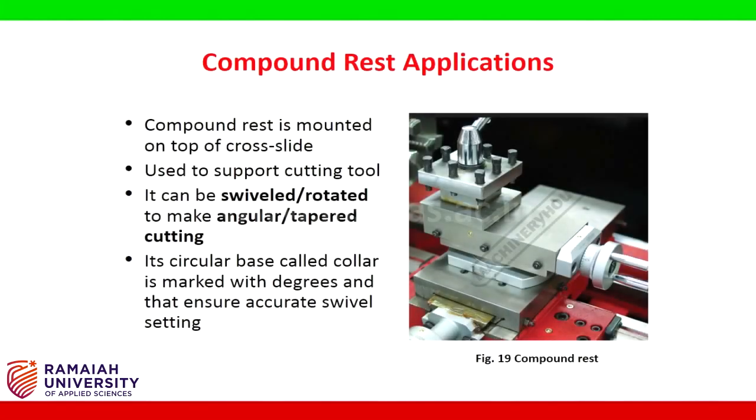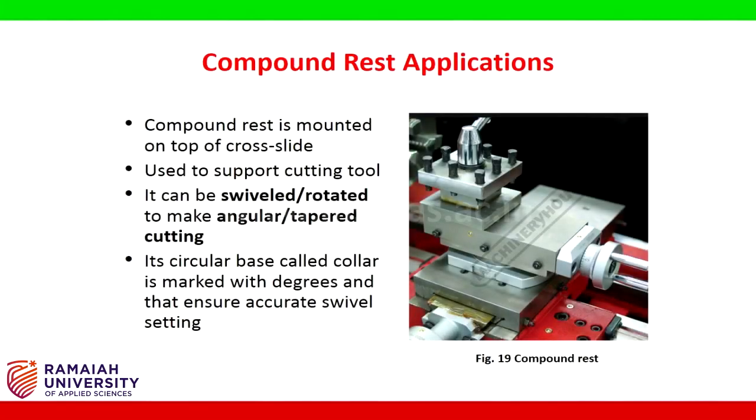Compound rest. Compound rest is mounted on the top of the cross slide. It is used to support cutting tool. It can be swiveled, rotated to make angular or tapered cutting. Its circular base called collar is marked with degrees and that ensures accurate swivel setting.